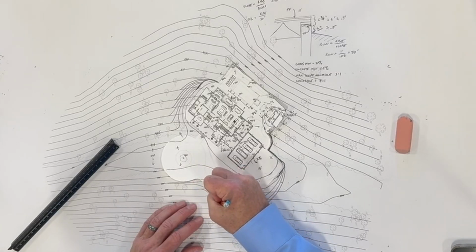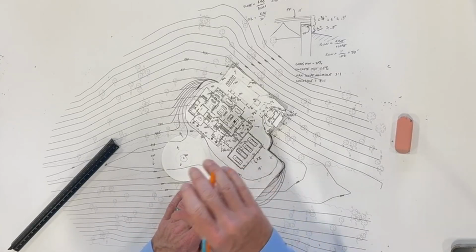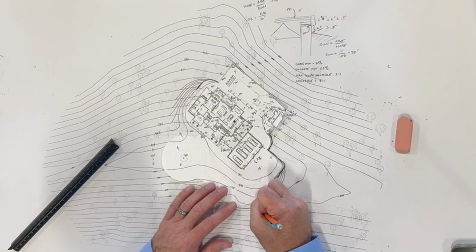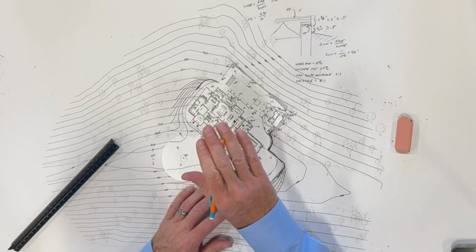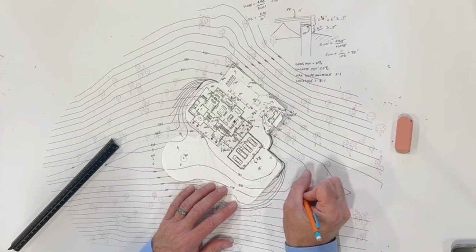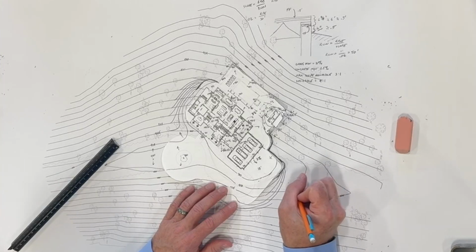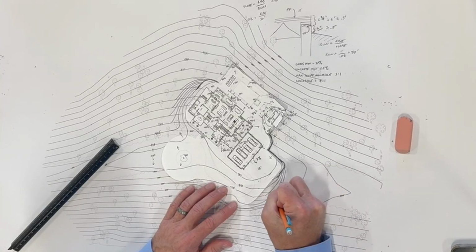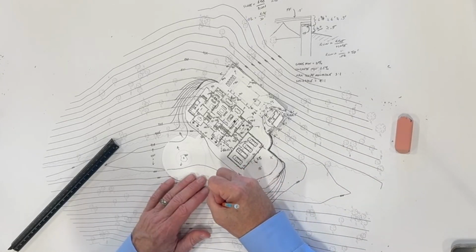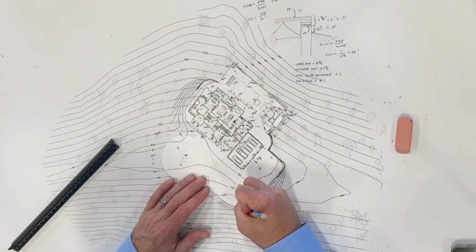935. Again, now as you look down this area, you're going to see this drop off, right? So this is dropping off. But still mowable, right? Because it's 3-to-1, so it's still mowable. Now here, this is good news, we caught it, right? So now we caught the contour on the other side. 934, because these lines cross, we're still chasing it a bit.